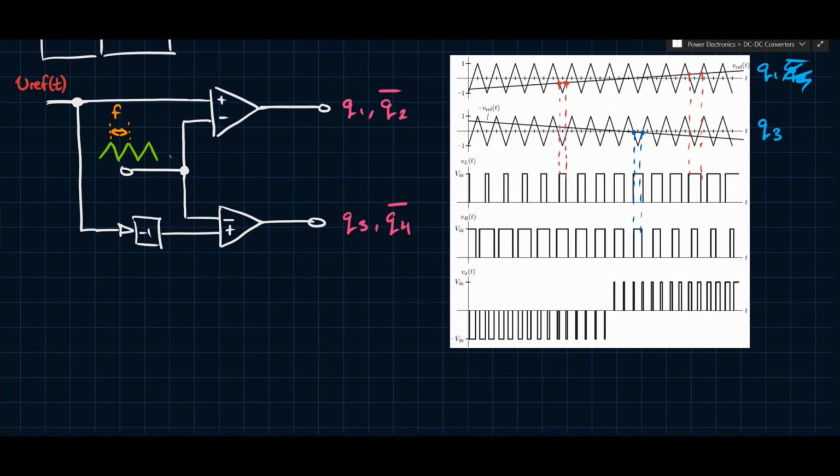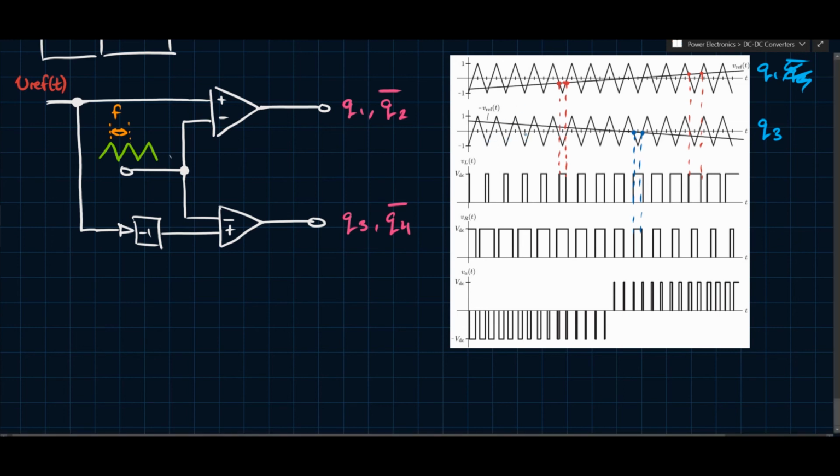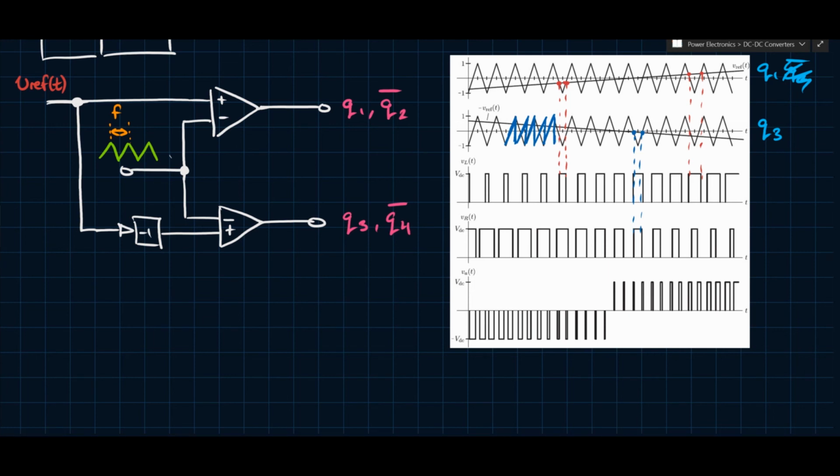This triangle is what we call a balanced triangle. It's not skewed. It goes up and down symmetrically. But you might have what we call sawtooth waveforms, which might do something like this, because these are easier to program. It goes up and then comes straight back down. These require less memory when you program them, because you can just repeat the cycle at whatever your frequency is, and you don't have to come back down.